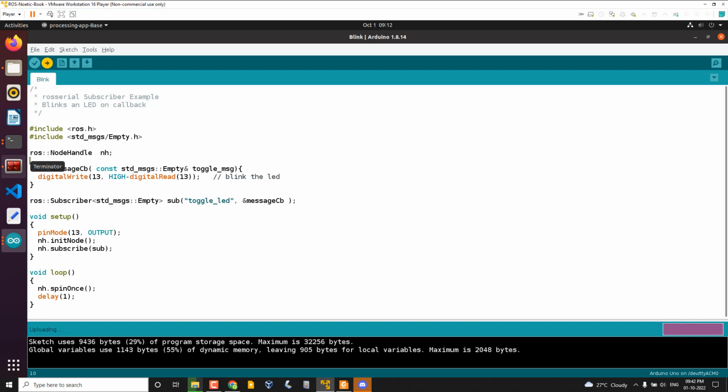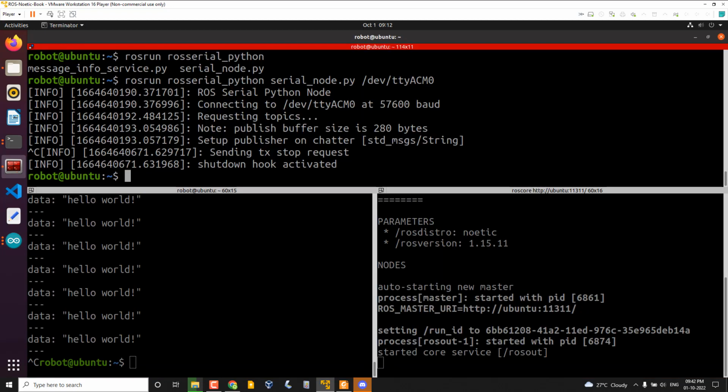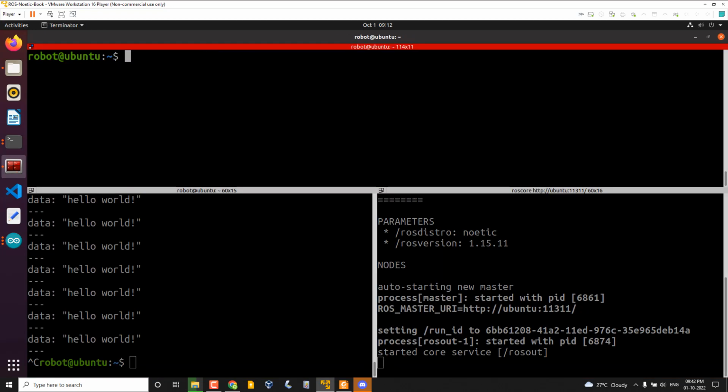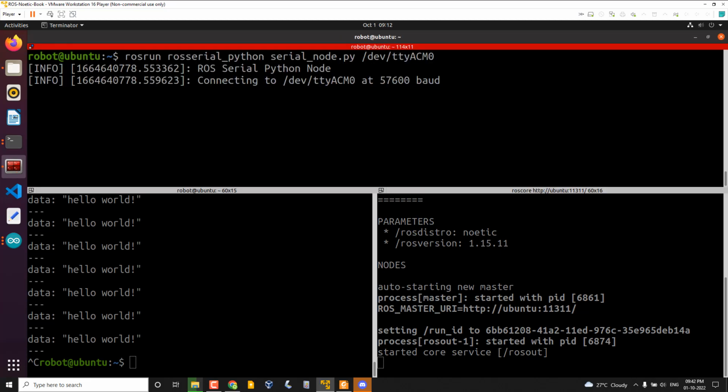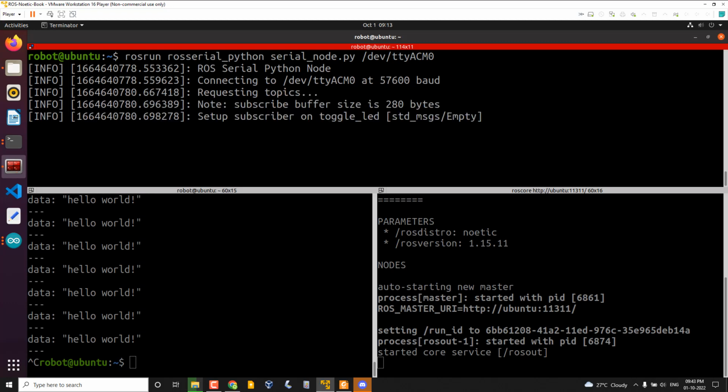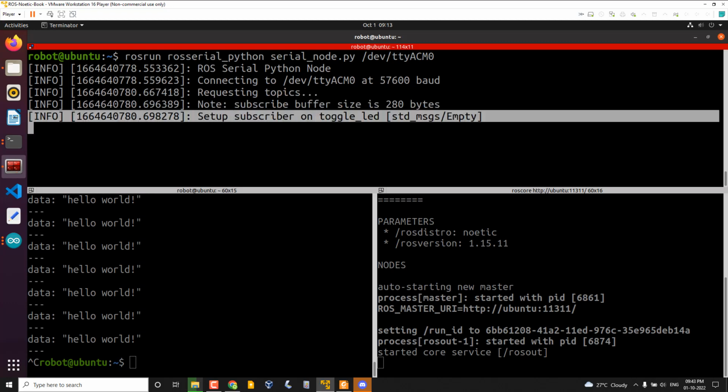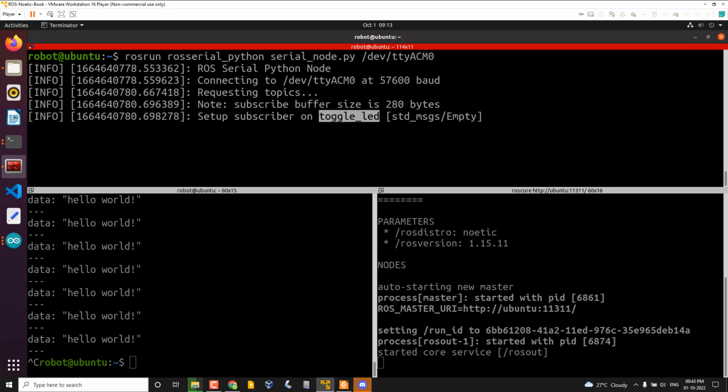Okay, the uploading is done. So the next step is, the ROS core is already running. I'm starting the serial node, and now when you run it, you can see there is a subscriber from Arduino, and the subscriber topic name is toggle LED. The message type is empty.